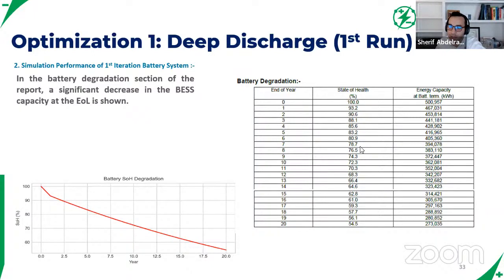So you'll notice that we went back and added more battery capacity, not changing the battery profile. When you add more battery capacity, that means you're using less of the state of charge range, which means you get less degradation, which means you're able to extend the state of health further into the future.